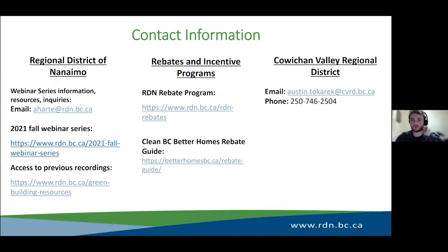Thanks Austin. It looks like we lost you a little bit there. The gist I got from that was that yes, definitely have it in the conditioned space, which I agree with. I think it'd be odd to have it in the unconditioned space. So we might need to look at the graphics we've included here. The takeaway is to put it in the conditioned space for sure. But even with that, you want to make sure you are taking care of where you're running your ductwork and that it doesn't go through those unconditioned spaces.